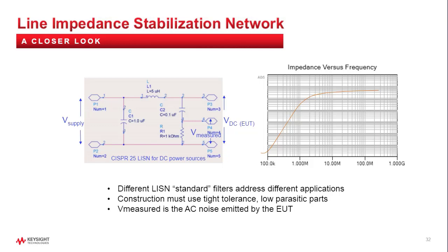Now, don't overthink this, but if you have a PCB, 1 ounce copper plating, let's consider a 4-inch wide power plane. What would be the equivalent American wire gauge, AWG, size? Don't overthink it. Don't go off and calculate it. It's not a difficult calculation, but I just want to get a perspective. And I personally was quite surprised when I did this. And I'm going somewhere with this. This isn't a random question. So again, 1 ounce copper plated PCB, 4-inch power plane. What's the equivalent wire gauge size?